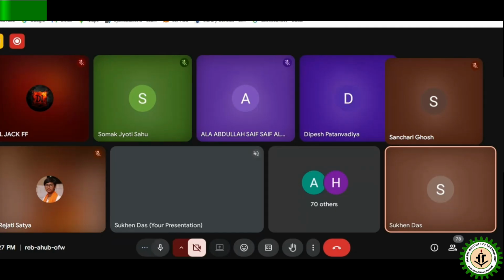The different streams are there, blocks are there, conversions are there. Now suppose over here, if you click on this line, this is the supply. I'm changing the stream name. I'm writing it as supply, SUP. And this is the delivery. I'm changing the stream name over here. So this is delivery. Now for supply, how much is the flow? You just click on the line. You see the flow is 150 meter cube per hour, at 35 degrees Celsius.